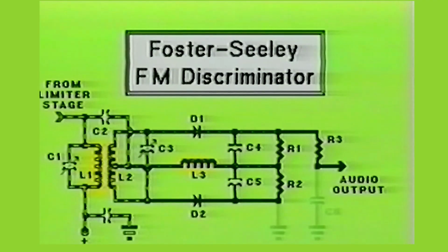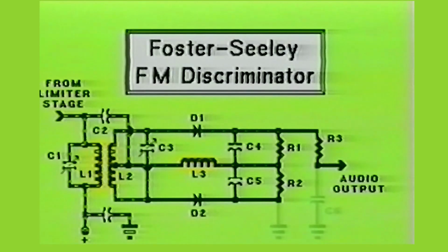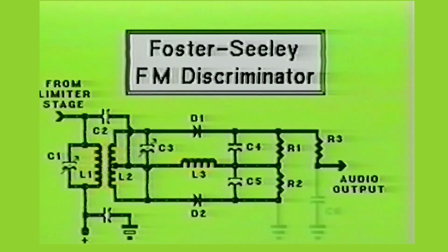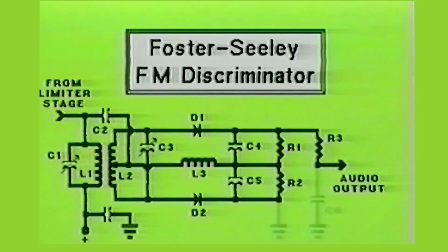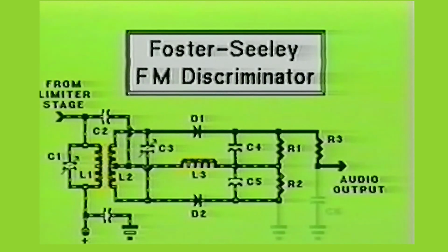Once again, ES1 and ES2 are no longer equal in value. Since ES2 has the greatest potential, resistor R2 and diode D2 will pass the majority of the current. This results in the voltage drop across resistor R2 being greater than the voltage drop across resistor R1. This causes the output of the discriminator circuit to produce a negative output.